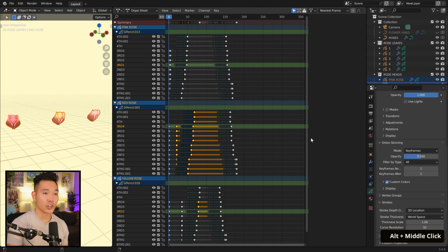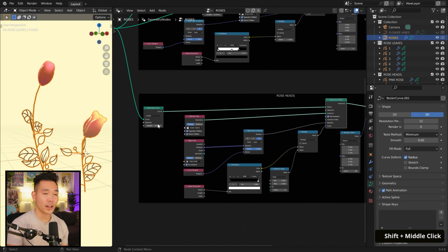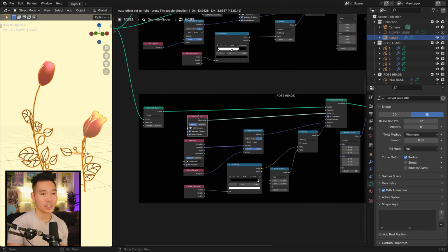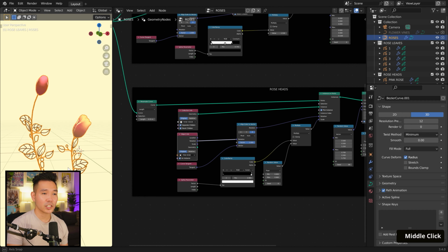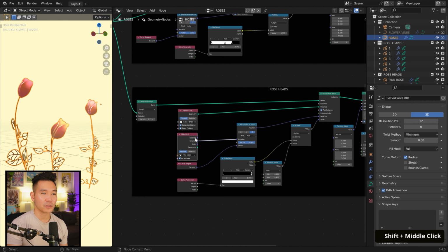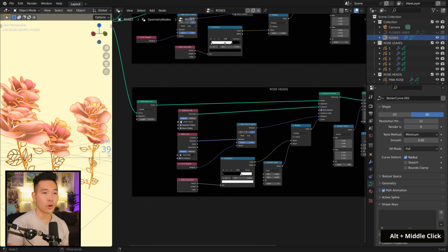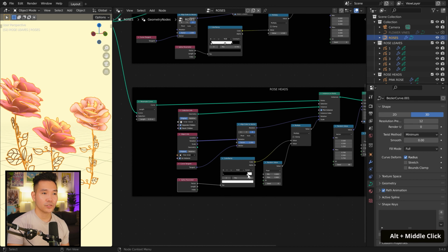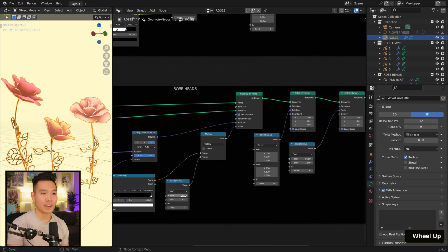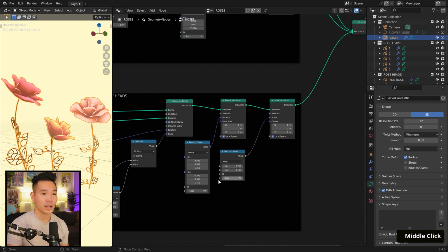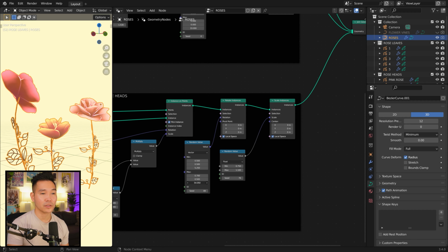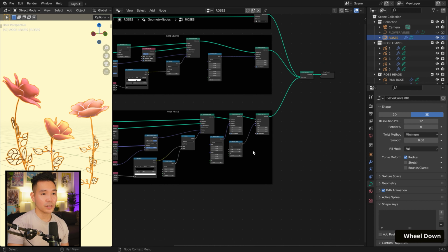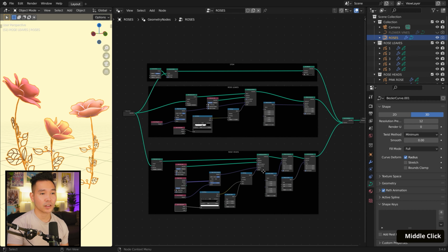Going back to the geometry node setup, I have the resample curve value set to accommodate where I wanted the rose to be visible, and in this case, it's set to 0.15 meters. Then I've instanced the rose head collection. For rotation, I've actually pulled in one of the instances and used their base rotation and adjusted it accordingly. Then for scale, I have it to where the rose heads only display at the very top of the curve. To the right of the instances on points node, I have a few more nodes to randomize the rotation and scale of the rose head each time a rose is drawn. Then I've used a join geometry node to combine them all together, leading to the group output node.